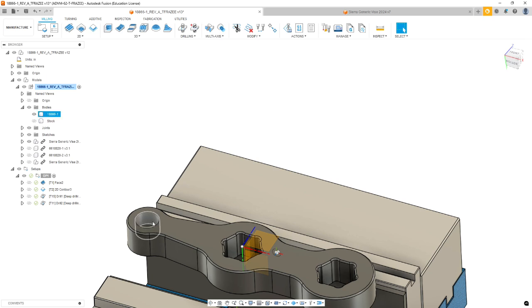We're going to cut the counter bore first. This is a tight tolerance according to our drawing. We may need to cutter comp this to make this come into print. So if we use it to make this feature, then come back and make these two features with it, at least at that point it will be first in the code, and we can start the program from there. We're going to do a 2D pocket.